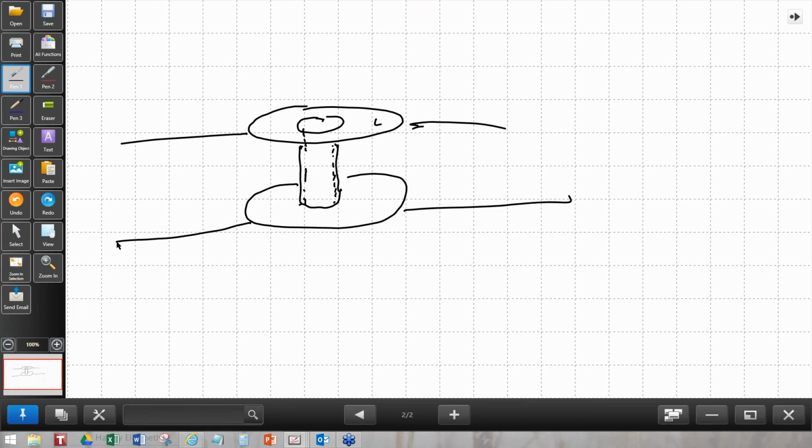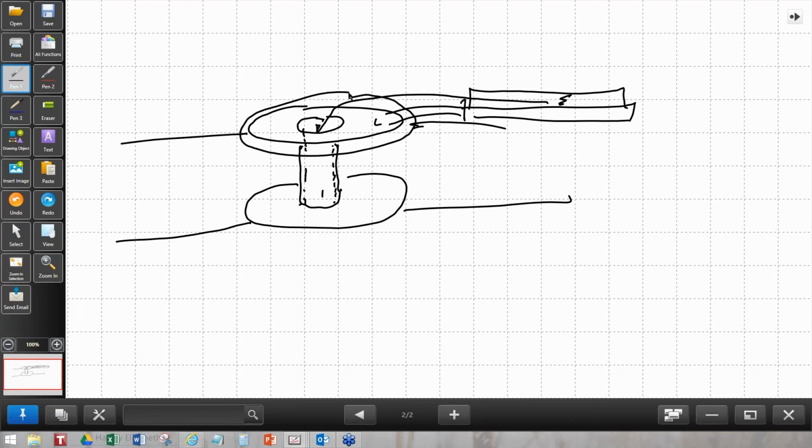We may not want to put this in, say, a wave solder bath because the solder would go down inside the hole, and that would suck up a bunch of solder. That may be okay, that may be not okay. If we have a pad over here and it's connected by copper, and we put solder paste on it, what we don't want to do is heat it up and have most of the solder paste end up going down the hole. So we typically put the solder mask coating on the outside of this.